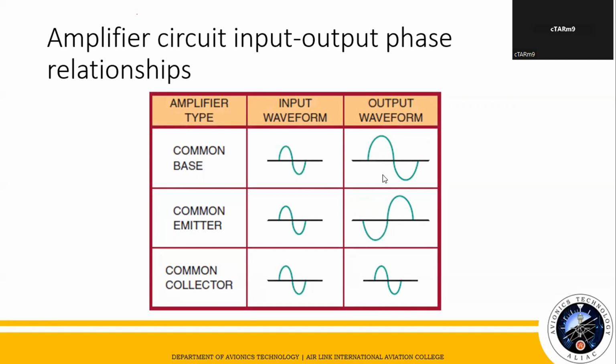Let's repeat: it minimizes signal reflection. In this circuit, the source and the load should be equal, so the input waveform and the output waveform are the same. In a DC circuit, the impedance matching circuit should have source and load equal. In alternating current circuits, the source should either equal the load or the complex conjugate of the load, depending on the goal.